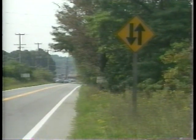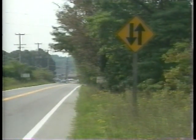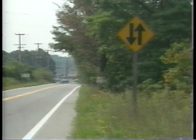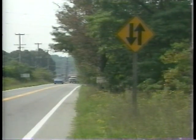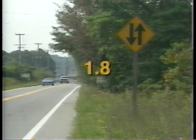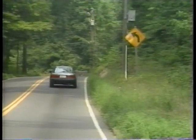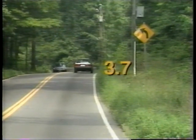Lateral clearance. There should be maximum practical lateral clearance to protect vehicles which may leave the road and hit a sign support. The recommended distance from the road is 1.8 meters from the edge of the shoulder. If there is no shoulder, the sign should be 3.7 meters from the edge of the traveled way.